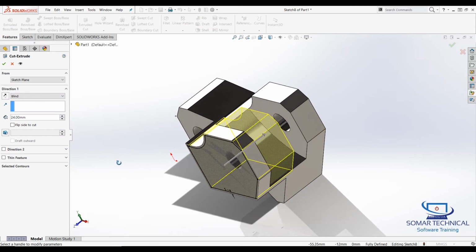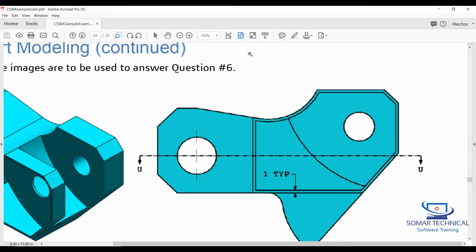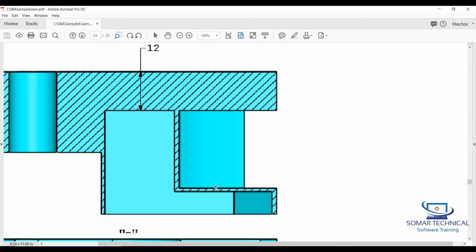It wants to basically cut everything inside of that shaded area. And the difference here is that according to the PDF, the back wall should also be a 1 millimeter thickness back here. So we're taking the extrude only to this depth first. This part here we'll do a minute later. But this one here is the first step that we're doing.